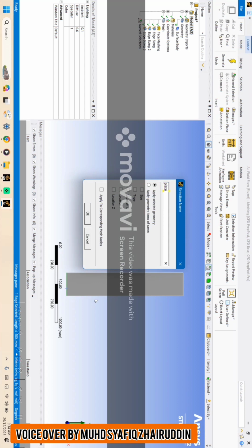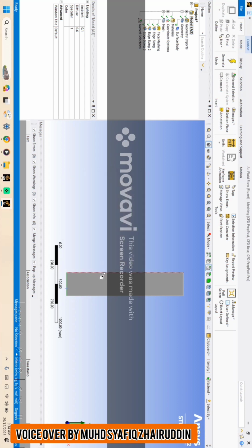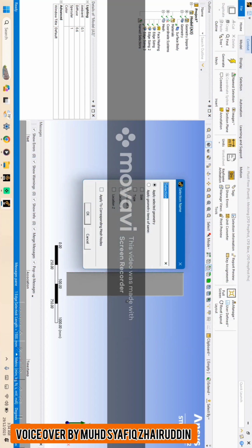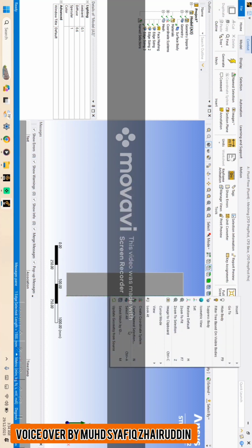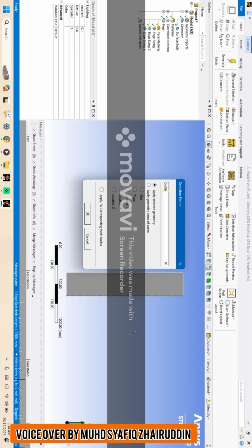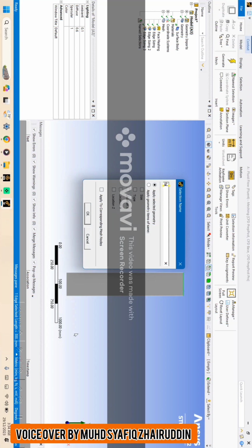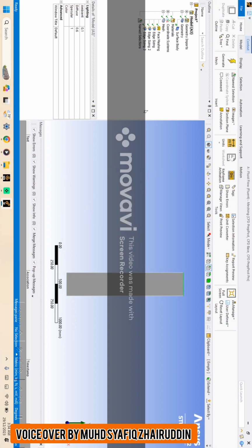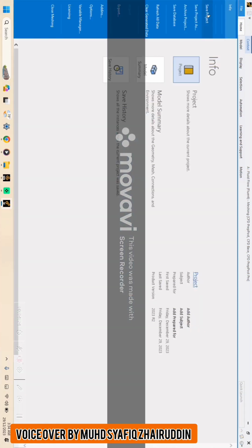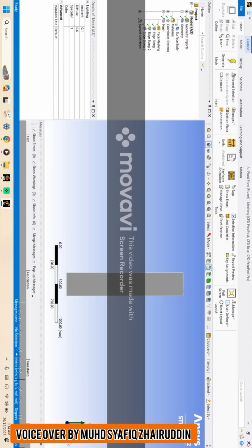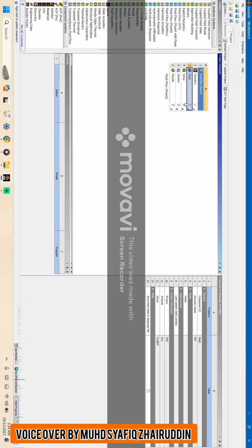Firstly, for the bottom boundary, I right click and rename it as plate, and the right boundary I rename as outlet. The left boundary I rename as inlet, and the top boundary I rename as far field pressure. Now you can save the project again and close the meshing,